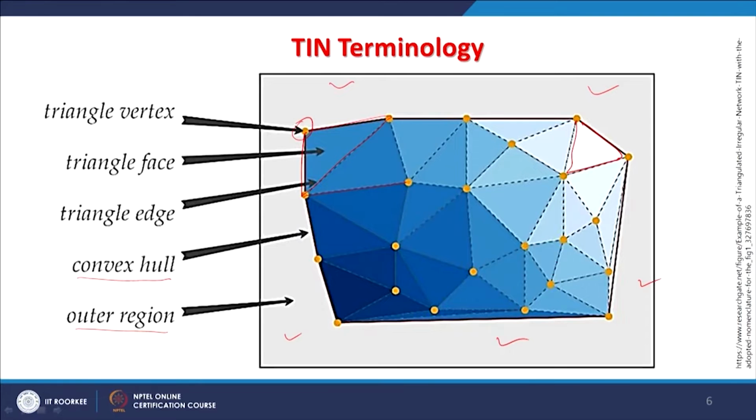So if all points are aligned like this point, this point, this point and this point, and we have to satisfy the Delaunay concept or theorem, then these triangles are made, but very elongated ones. And though there are triangles, there cannot be any other shape of the unit. The unit here always has to be the triangle.